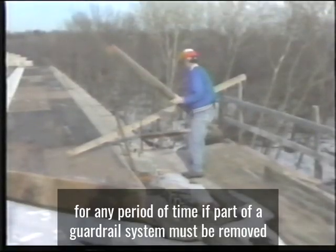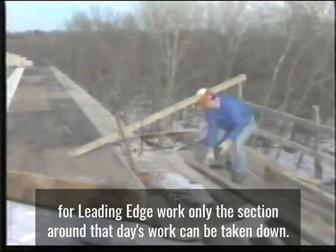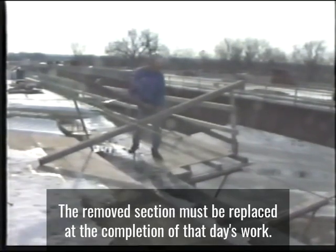If part of a guardrail system must be removed for leading edge work, only the section around that day's work can be taken down. The removed section must be replaced at the completion of that day's work.